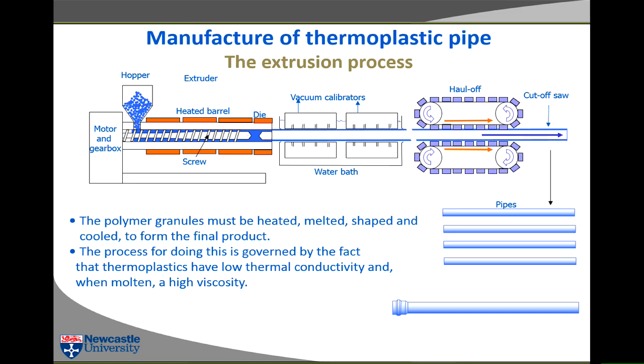I don't know which diameter you go for with steel. Any thermoplastic pipe that you buy, you will specify the outer diameter and the ratio of the wall thickness to the diameter. You can actually make pipe with an accurate inside diameter, but it's hardly ever done.